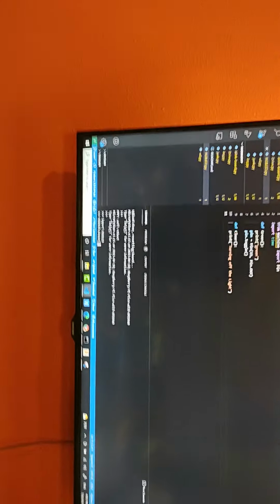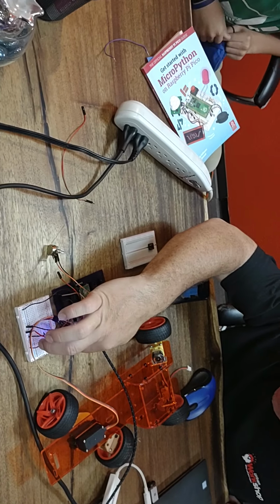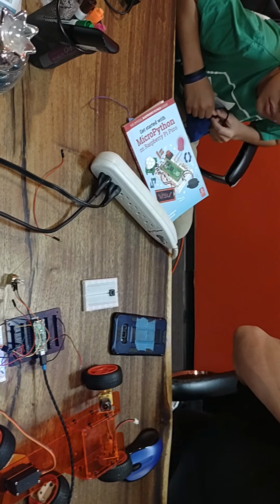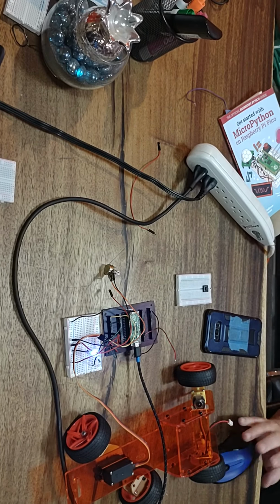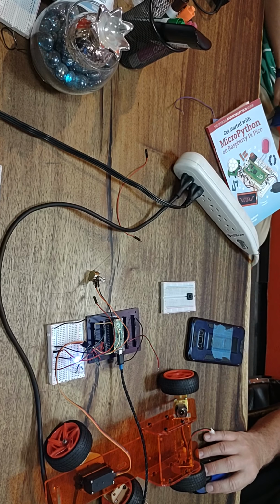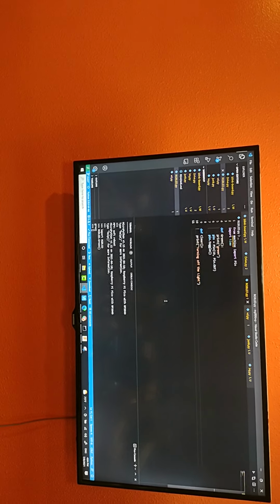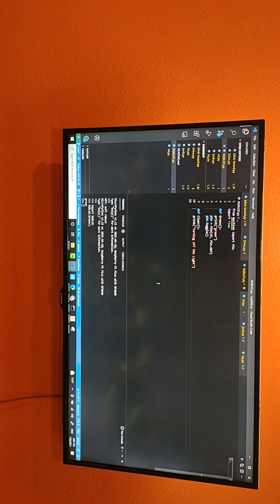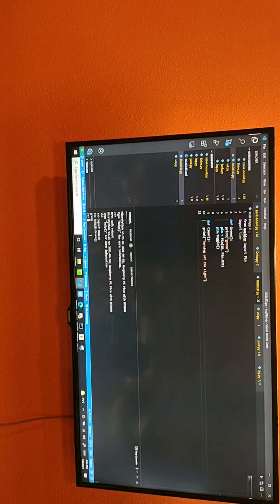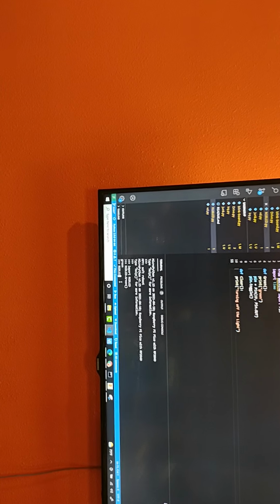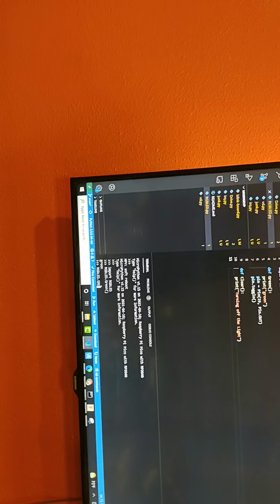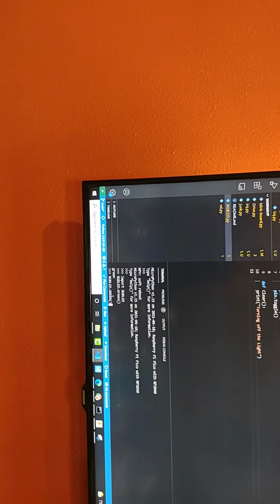What's in it? And then we got green. It'll be blue. There it is. I want to fix that. Move the resistor over to the next pin over there, but that's just how it is right now. All right, so you just addressed pin 19. You gave power. Pin 19. Yep. Since I got a toggle, I know if I want to turn it off, I do the same thing. I'll just turn it off again.